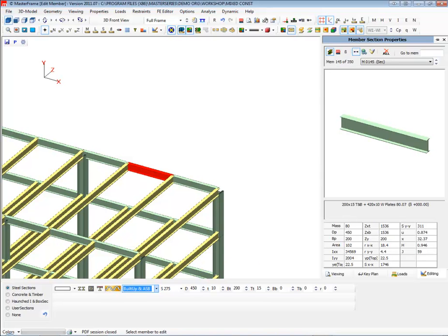Now, finally, and I think this would probably be the last question, Johnny Moffat has asked the effective length for design of a curved member. Well, hopefully, Johnny, most of your curved members would be fully restrained, and therefore we don't have an effective length to worry about. Other than that, I don't have any guidance on what you use, and I can't really advise you. And that's one of the reasons why I suggest you try and create your curve using as few members as possible, because I don't see you having a curved roof or anything like that that's not got some intermediate stays and restraints. So I would use those to create my facets.